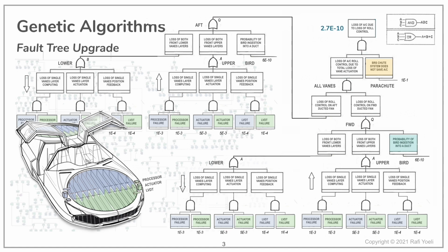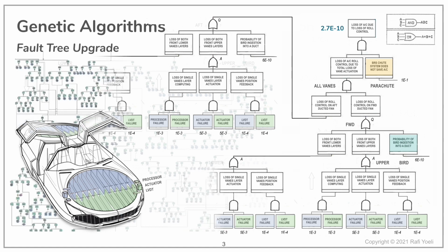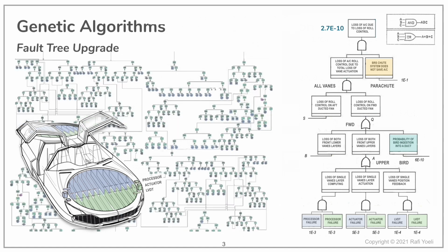The calculated probability of that comes out as 1 in 27 billion per flight hour, or 2.7 e-10 in scientific notation. All of that sounds complicated, but is in itself quite simple math. There are special programs that perform fault tree analysis once we have constructed the tree itself, representing our system correctly. Modeling the full system into a tree diagram is of course a tedious task. However, much more so is the effort of putting together the system in the first place, be it a ship, a satellite or an aircraft.